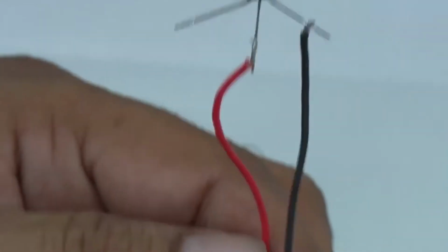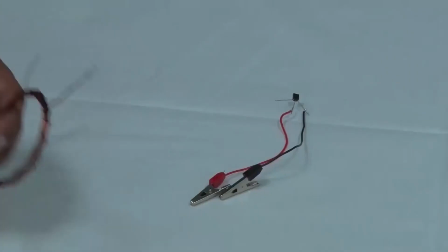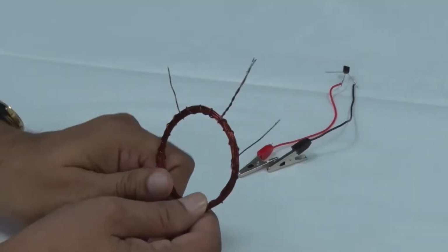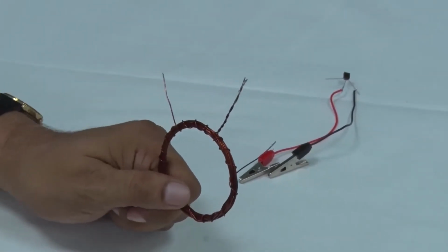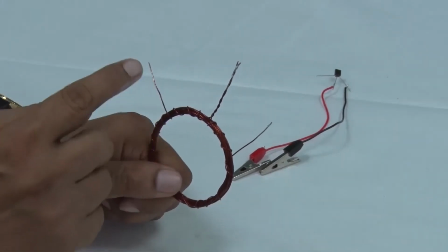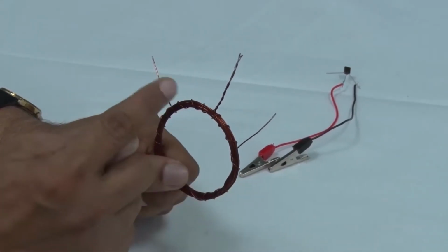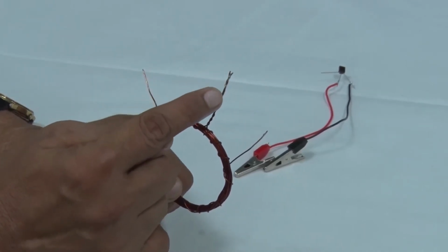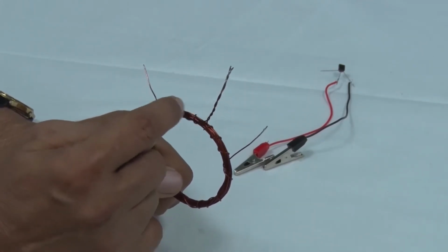So we have added 2 clips here, and then let me tell the other part of the circuit. This is a handmade coil of copper wire, and you can see there are 3 terminals coming out, here, here, and here. How can a coil have 3 terminals? What we have done is 30 turns total. Starting from here, we make 15 turns, and after 15 turns are over, the same wire is taken here, and then this part is taken out, a central tap, and it continues.